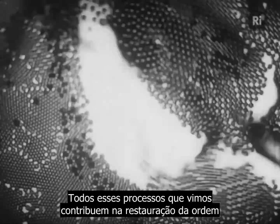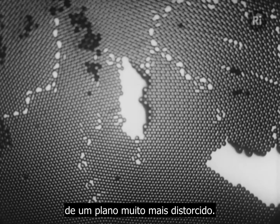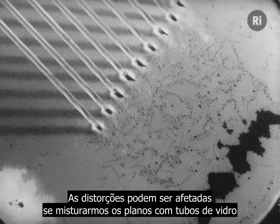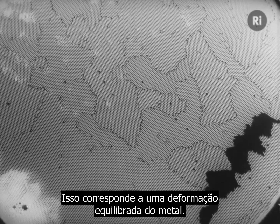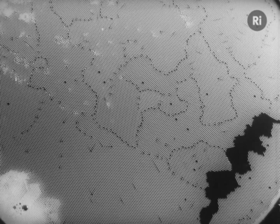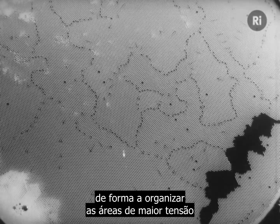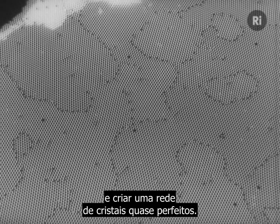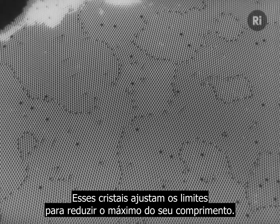All these processes we have seen play a part in restoring order to a much distorted raft. The distortions can be effected by stirring up the raft with glass rods. This corresponds to a violent deformation of the metal. The dislocations travel and combine so as to tidy up the areas of greatest strain and create a mass of nearly perfect crystals. These then adjust their boundaries so as to reduce their length as far as possible.